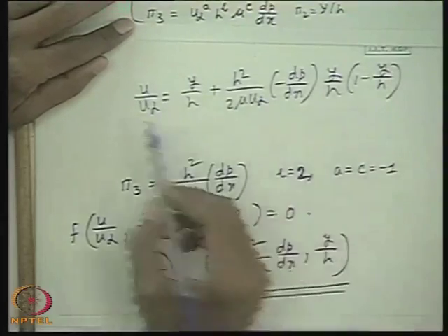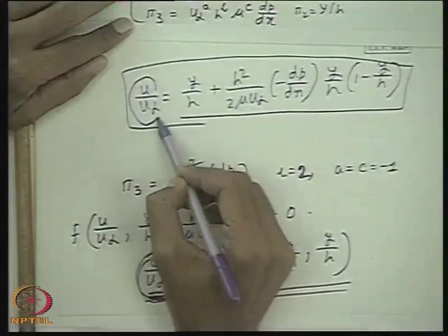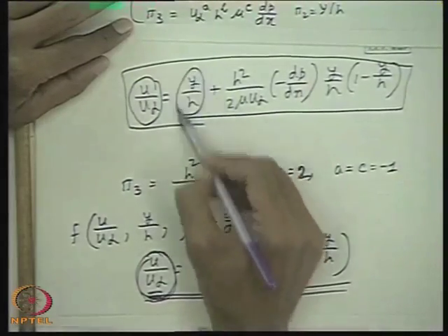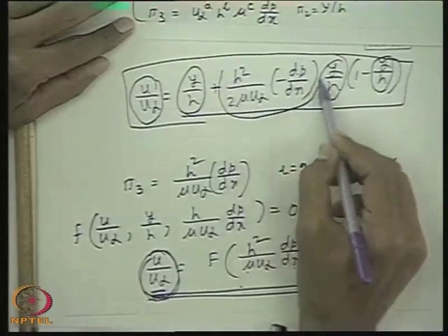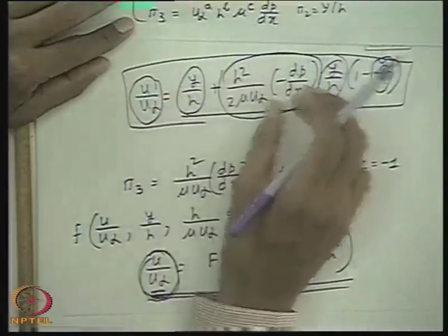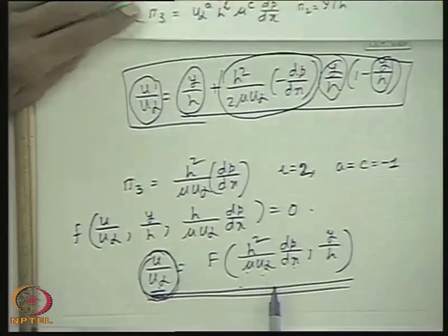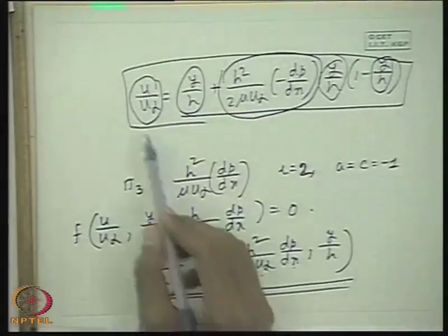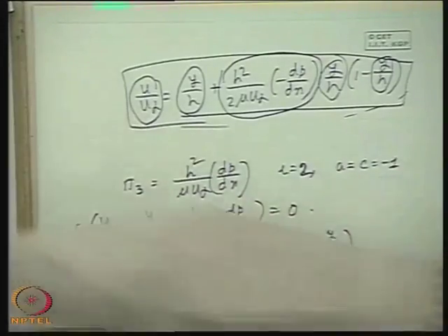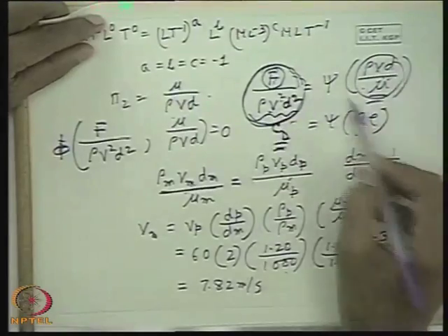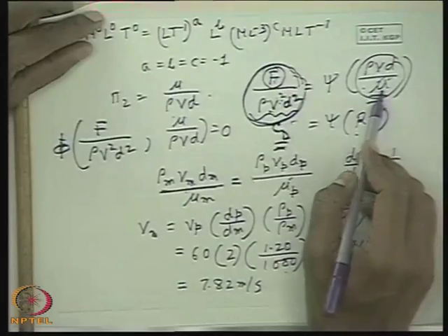Now here the problem is that here we cannot express this explicit functional relationship. We can only recognize that this is the dimensionless dependent variable, this is one non-dimensionless independent variable, it is another dimensionless independent. So only the dimensionless variables, both dependent and independent, we can fix. But by Buckingham's Pi-Theorem or dimensional analysis, we can never find out the actual explicit relationships. For example, the earlier problem also, the drag force is a function of Reynolds number. What should be the explicit form of the functional relationship is very difficult to be established by dimensional analysis.